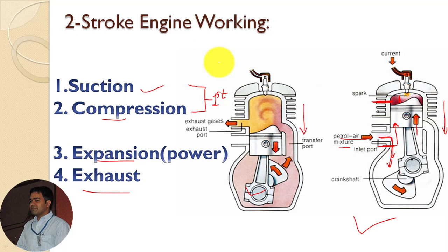So when the piston starts downward movement from top dead center to the bottom dead center, this process of downward movement is due to the push type forces produced by the hot flue gases. So our expansion process has started, and during this we are getting some power output at our crankshaft, and that's why this is known as a power stroke also.